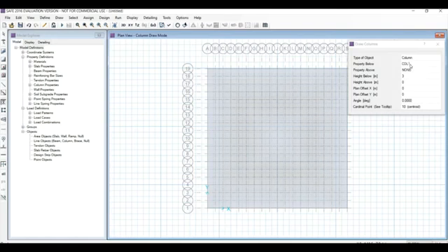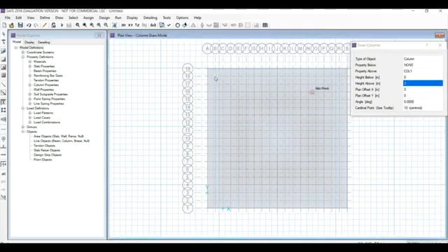Column 1, below is none. Make sure that below is none. Above is column 1. Height below is 0. Above is, let us assume, 2 meters of plinth beam level. Then go for 2, and then draw the column. Column 1.